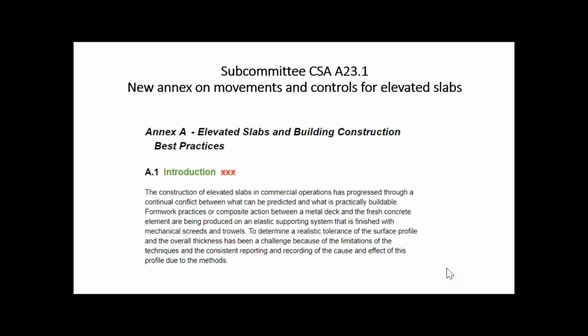Our best practices guide has subsections which include formwork setting, concrete placing, reinforcing setting, post-tensioning, design approaches, and sensitivity to empirical versus calculated approach, including materials choices, measurement and case history examples. Materials properties like creep, shrinkage, tensile strength, MOE, etc. are important in working towards the calculated approach. So this is going to be a very extensive section. It'll probably be between 10 and 20 pages, and it should help the practitioners in the various areas to work towards something that is more comprehensive than is available right now in the industry and throughout literature, which is why we're writing this up now.